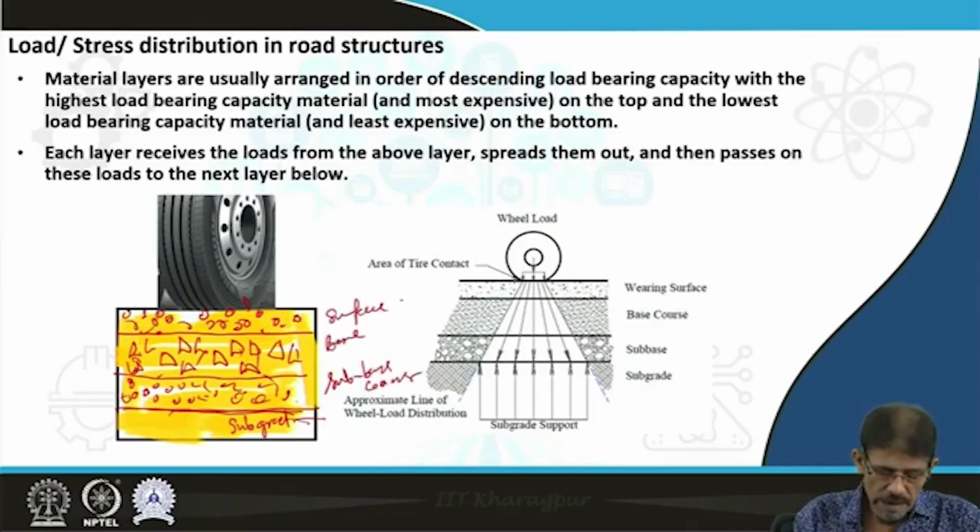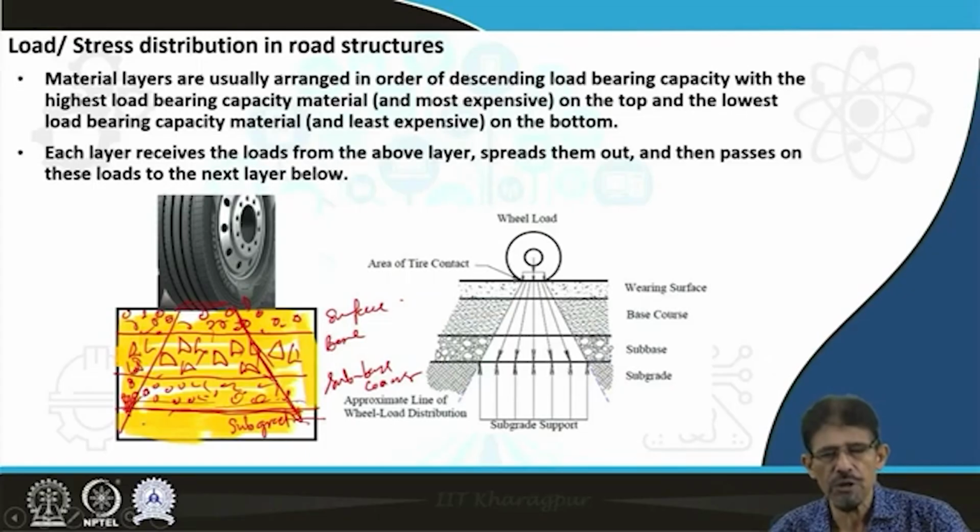In these flexible supports, the live and dead load of vehicles coming through the contact between this road and tire is going to diverge downwards, deviate from the original area width of the tire and be distributed over a large area. Therefore, the deteriorating impact of such stress distribution is very negligible. Therefore, highways and expressways are generally preferred to be constructed with the help of flexible support.